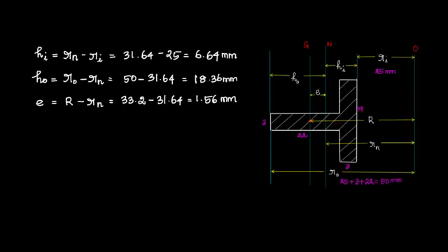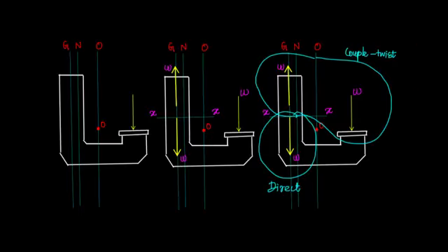Load by area is the simple formula for stress. What will be in the area? Dimensions. So we should know all the dimensions and we should know the stress value which is given in the problem, then we can calculate the load value. Okay, so we can analyze the diagram to identify what are the different stresses that will be induced in the particular curved beam. Let me see the first diagram.